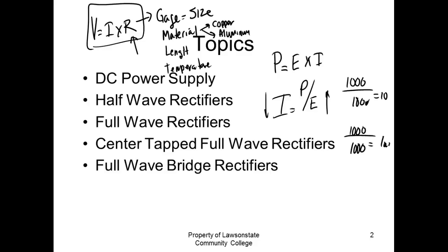They do a little bit because there's no such thing as a 100% efficient transformer. But most of the transformers now are well over 95% efficient, which means if I get 100 watts out, we might put 105 watts in to get 100 watts out. So for practical purposes and for approximation, we'll say that they're 100% efficient.